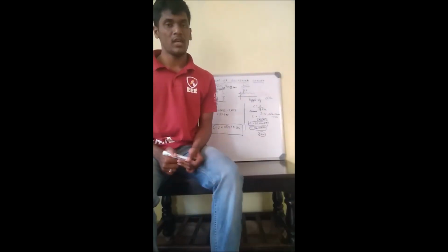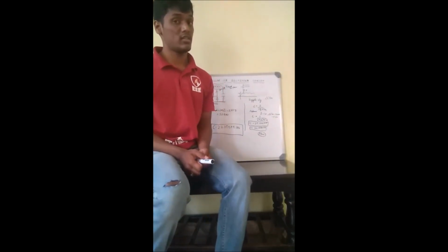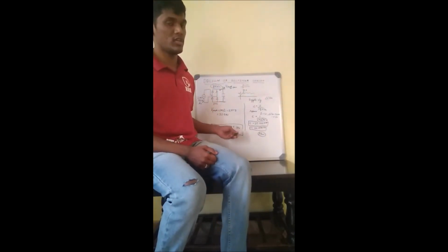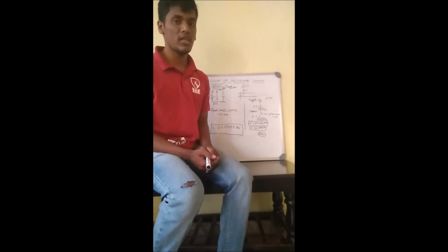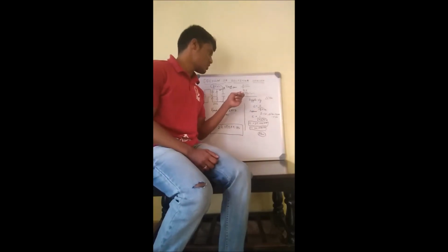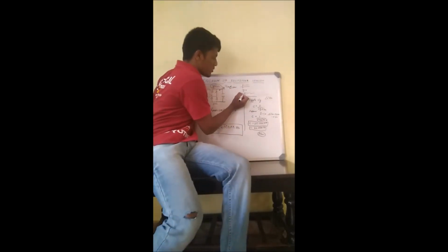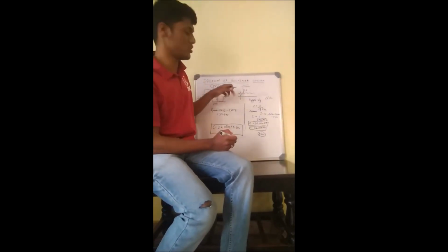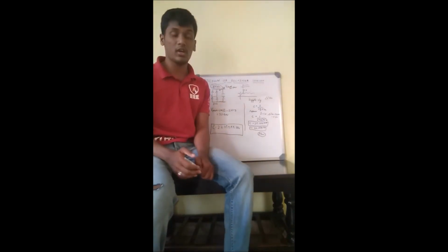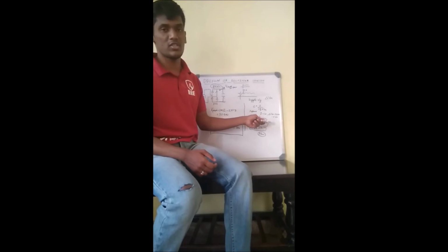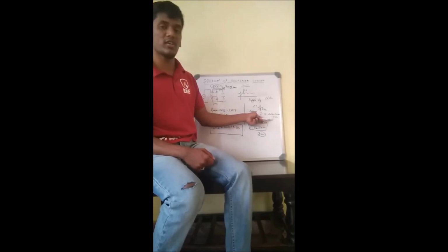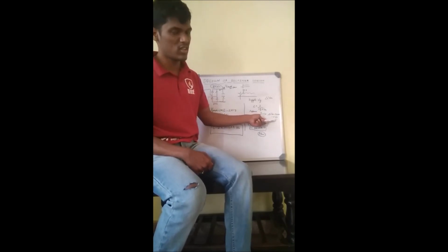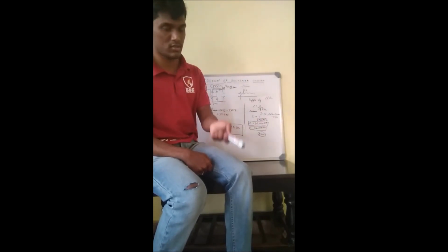So till now I have explained how to find the value of the capacitor with the voltage rating. Now comes the output voltage. So what would the output voltage be? The output voltage will be varying from this point to this point. You may say this variation is quite negligible, since the ripple voltage is just 0.5 volt. Some people won't entertain even this.